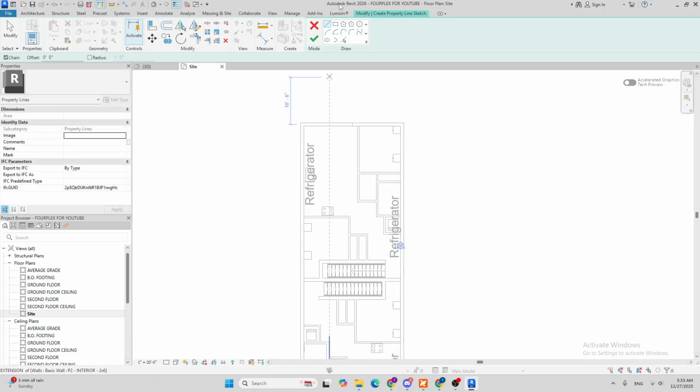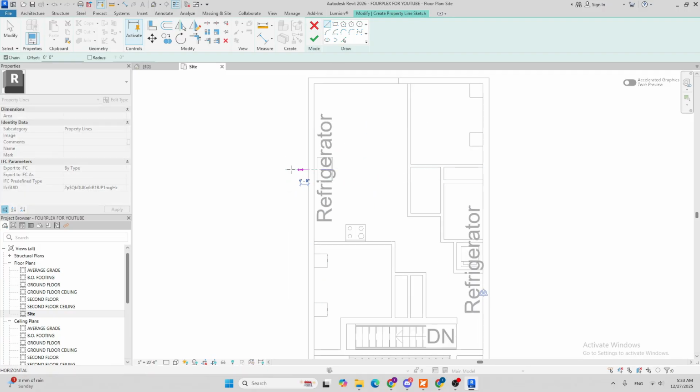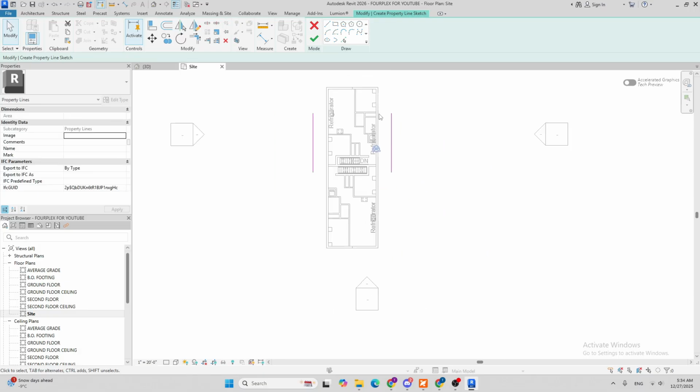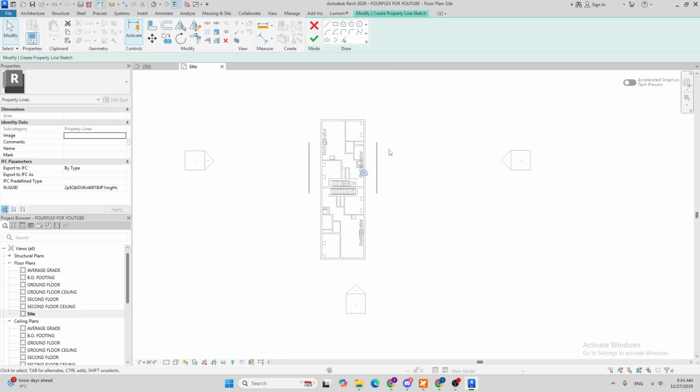I'm gonna go sketching, right? So I'm gonna click the wall, and I'm gonna go 6 feet this way, escape, and I'm gonna go from the wall 6 feet this way, and I'm gonna draw down. This one I'm gonna draw down as well, and I'm gonna hit escape, and delete these two lines. Okay, so that's our two. I'm not gonna draw the full thing yet. I'm gonna draw these lines, and I'm gonna trim and extend it later.